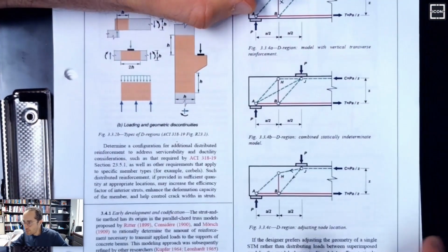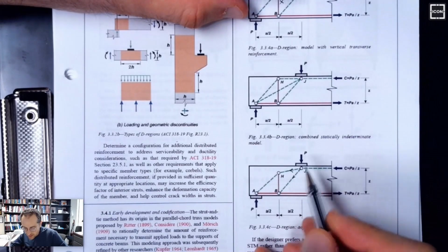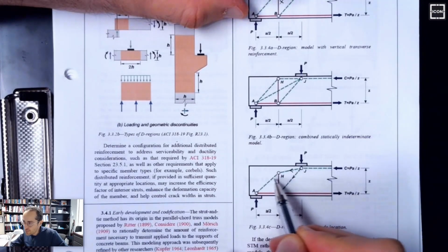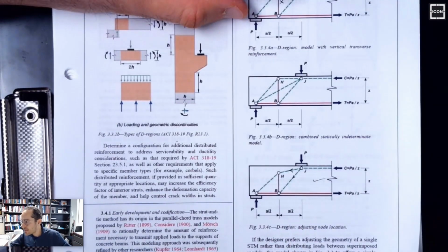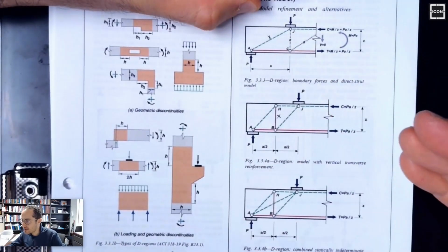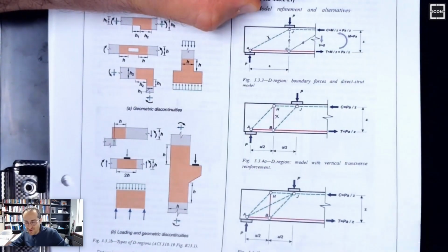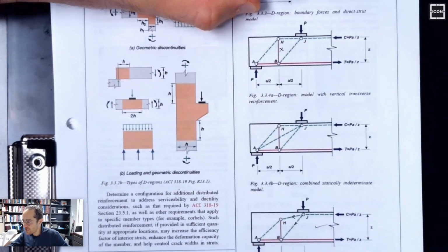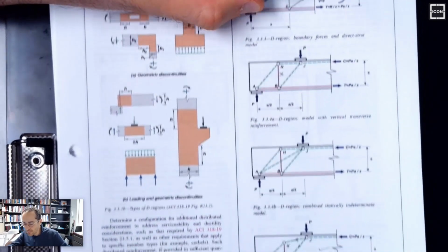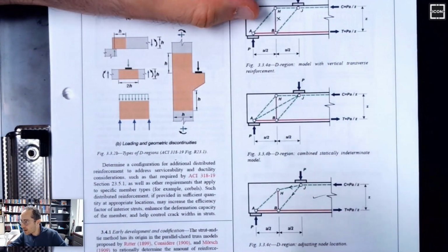In this case, I proportion it such that I would send only the tie capacity to this one and whatever remains to that one, but I'm pretty good with the angle because I'm also improving the angle, so more than likely this might pass. If your original model fails badly, let's say you have 100% overload, maybe nothing passes. So don't expect to gain huge capacities by going to a more refined model, but if you have maybe 20-30% overload, something more manageable, then you can always refine and try to get larger capacity out of the system.